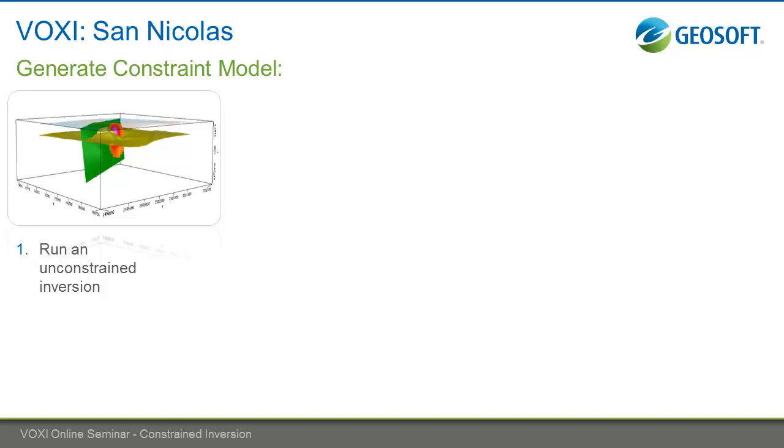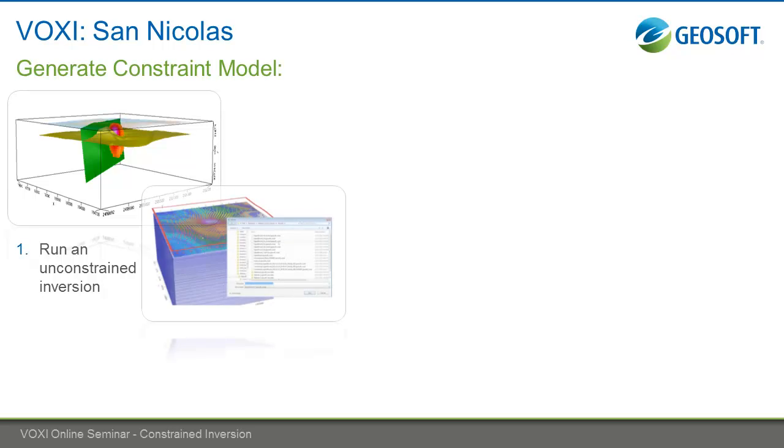So when I've run my unconstrained inversion, I've obviously got a mesh that has been used in that unconstrained inversion. The first thing I do is export that mesh to generate the general voxel structure that I need. So the mesh just is exported, and in essence it has no voxel values in it. Now I need to populate that mesh with the appropriate values for the upper bound constraint.